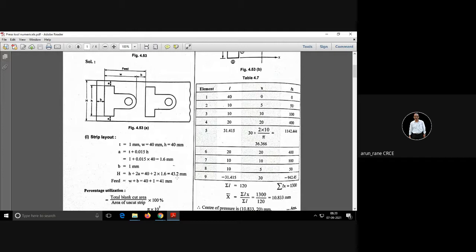Now you have to check in the market whether this 43.2 millimeter width strip is available or not. If it is not available, because this is an odd size, then if your quantity is large, like 5 tons or 10 tons of this strip, you can directly contact a steel manufacturer like Tata Steel, Mukund Iron and Steels, Jindal.